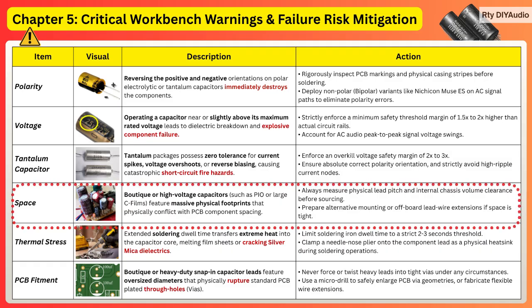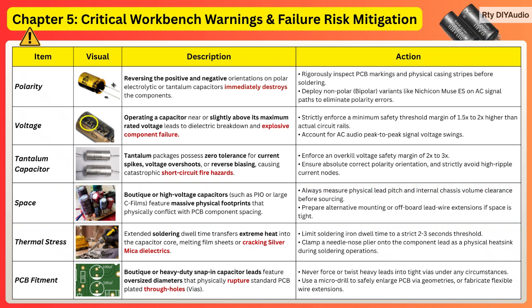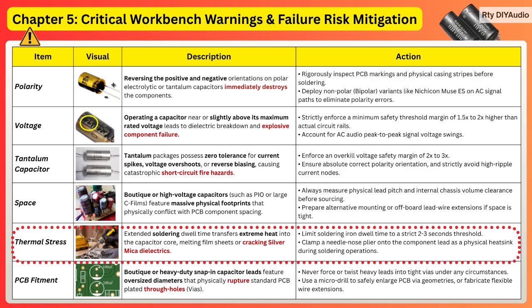Fourth, space limitations. Boutique or high-voltage capacitors feature massive physical footprints that physically conflict with standard PCB component spacing. Always measure your physical lead pitch and internal chassis volume clearance before sourcing, and prepare alternative off-board lead wire extensions if the chassis space is tight. Fifth, thermal stress. Extended soldering dwell time transfers extreme heat straight into the capacitor core, melting film sheets or cracking delicate silver mica dielectrics. Limit your soldering iron dwell time to a strict 2 to 3 second threshold, and clamp